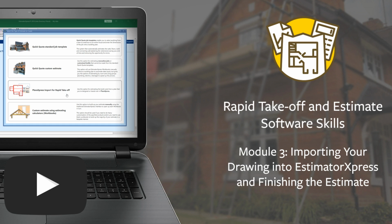It's worth noting before we begin that ideally you want to complete your plans before importing them into Estimator Express. It is possible to re-import your plans if you subsequently adapt them, but any changes you've made within the estimating calculators will be overwritten.